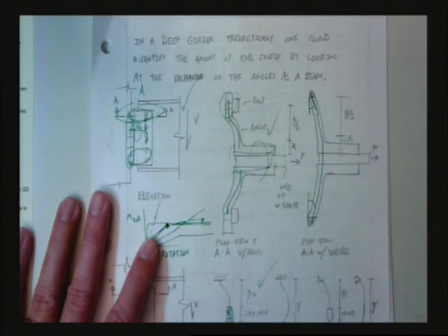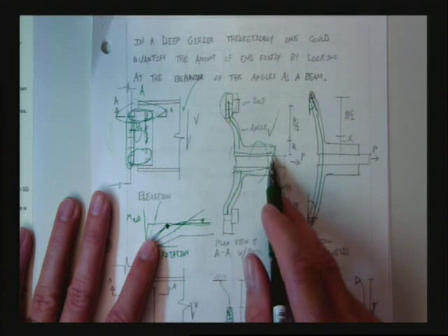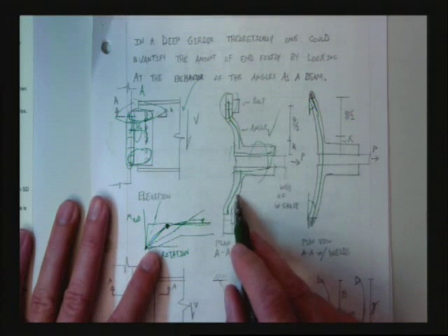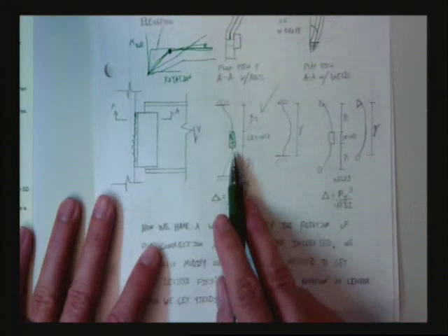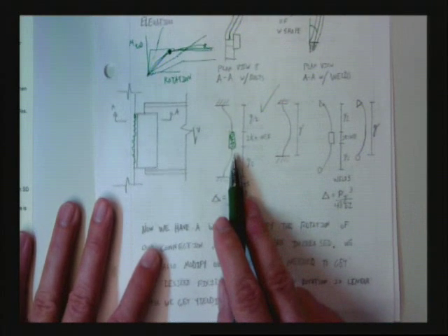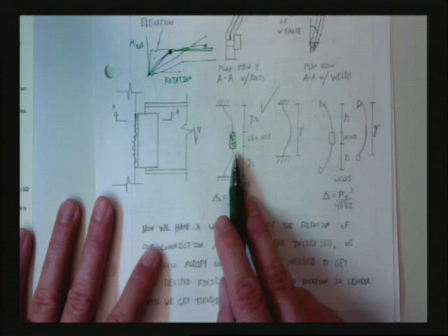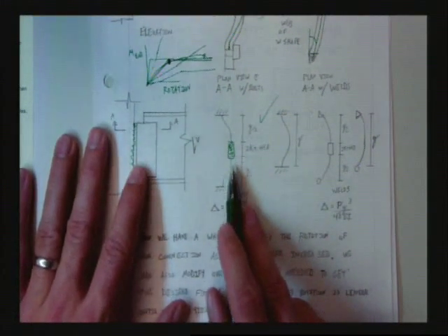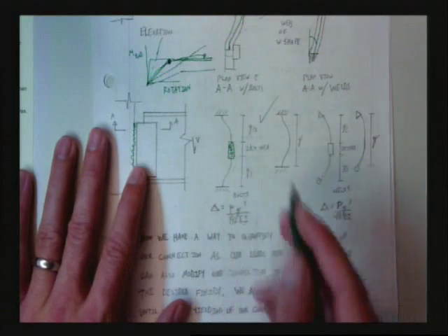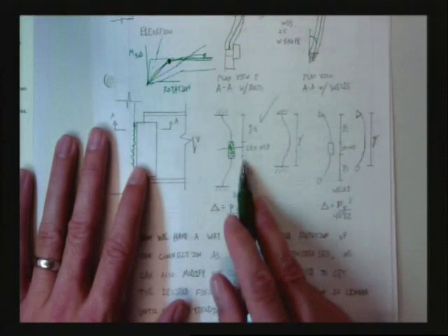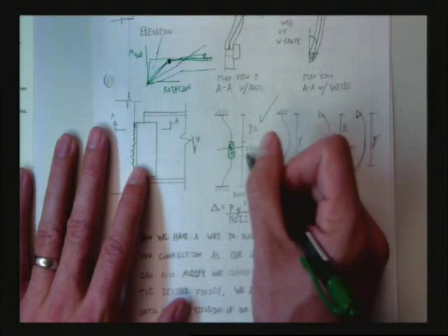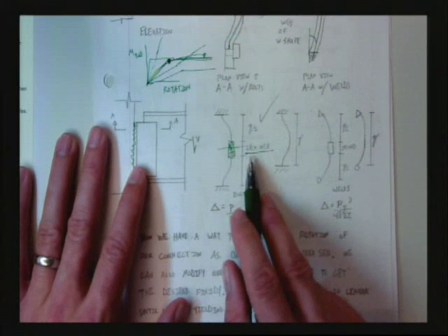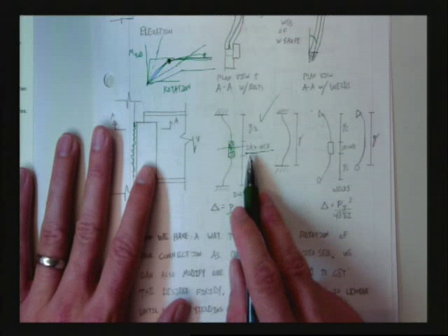That's why it's important. It's way more stiff than this. Right? Way more stiff. So we're going to call it infinitely stiff. You okay with that? Now, I'm not really used to dealing with things that are infinitely stiff, but since it's symmetric, I can actually simplify this. And I say this infinitely stiff area is equal to 2K plus the thickness of the web. What's K?